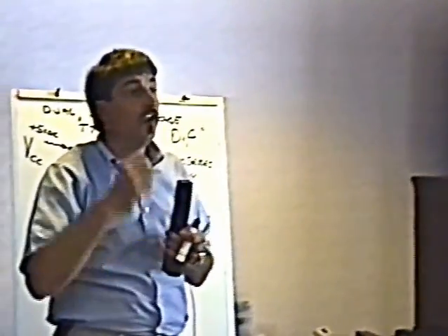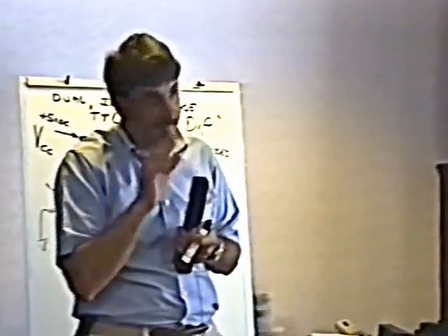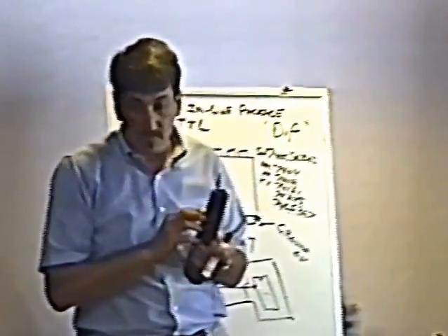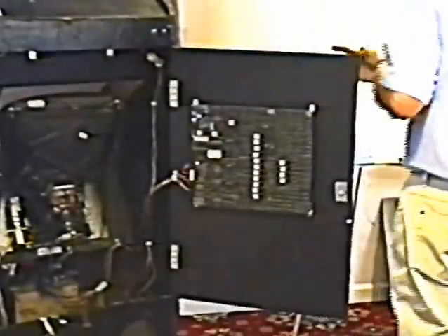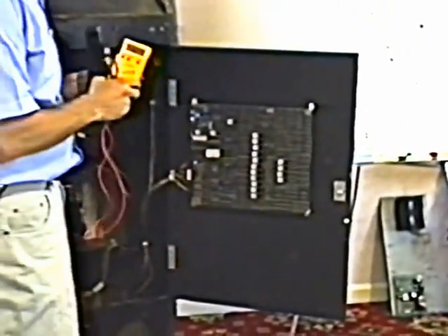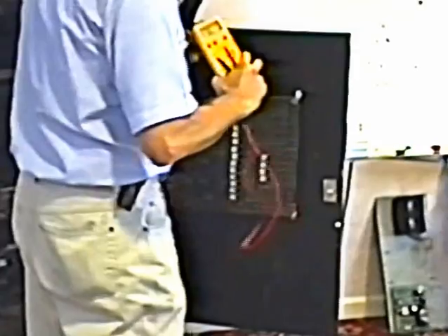You have a board failure. You have an input failure. Very common problem. And you can find that with your meter. Here's how you do it. Really a neat little trick. Since these integrated circuits are made of transistors, we can find this problem with our meter set on the diode test setting.